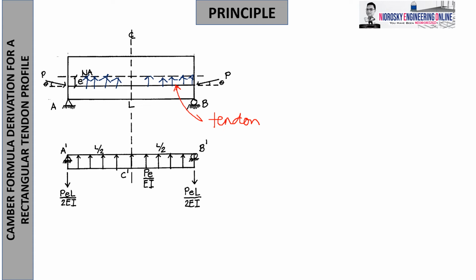Now, this is where we focus. We need to identify what deflection will be produced at the middle. Usually, a pre-stressed concrete beam has a symmetrical portion, deliberately so, at the centerline where the maximum deflection is. Notice that the loadings are always symmetrical. So we look for the deflection at the middle, which is why C' exists, a new letter to introduce. Your main objective is to get the moment at C'. If you recall, the fictitious moment, the one with the prime, is equal to the actual deflection. That is the concept of the conjugate beam method.